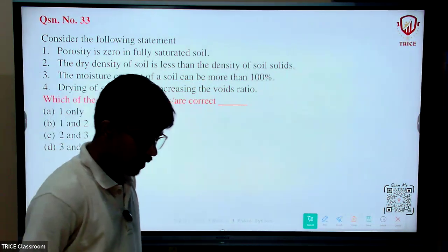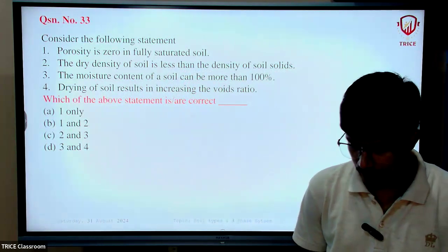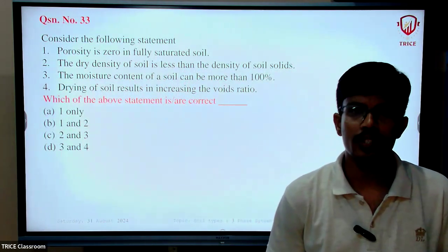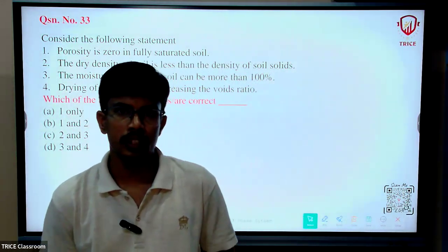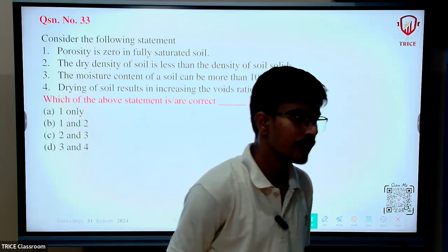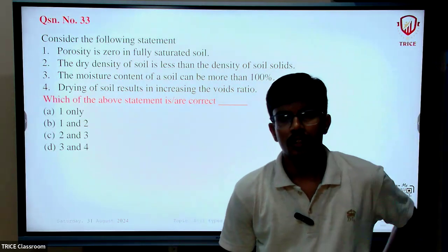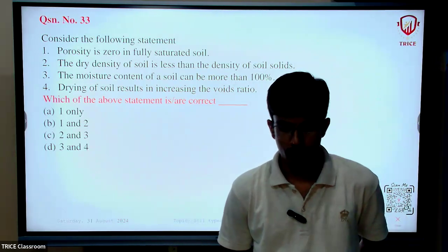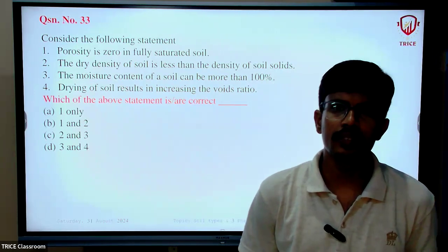So far I have covered the soil from the engineering point of view. Then how weathering occurs, the physical and the chemical portions. Physical weathering may be due to seasonal temperatures, splitting action of roots, splitting action of wedges, and flowing water causing abrasions.